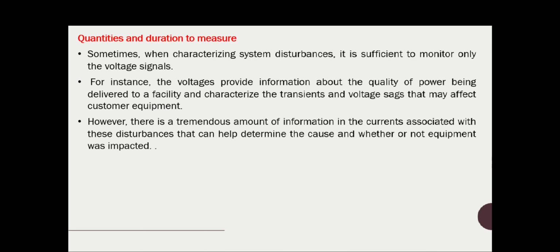So that is one consideration before going for power quality monitoring. And the duration of the monitoring depends upon the monitoring objectives. For example, if the objective is to solve the problems caused by voltage sag during a remote fault on the utility system, monitoring may be required for a significant length of time because system faults are probably rare.